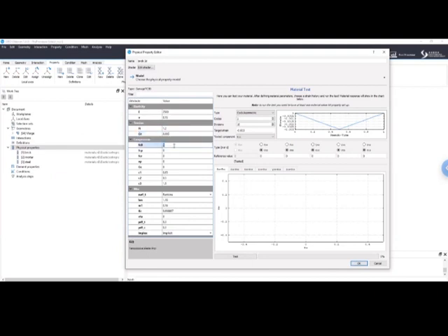Then this one is the tensile behavior. Now we need to define the compressive behavior. Here we have the compressive elastic limit. In this case, it was 20. And then the peak compressive strength was 26. And this one is a residual compressive strength of 1 megapascal. This one is the compressive strain at peak strength. In this example, it is 0.02. Make sure that this value divided by the Young modulus should be less than this one. Otherwise, the compressive model will not work.